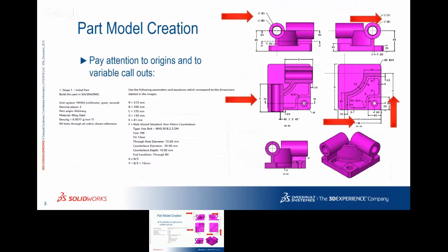So on this part, if you're missing things, like let's say you missed the chamfers, these 4 by 2 millimeter chamfers down here, that's going to affect the weight of the part. We typically tend to do tricky things like if you exclude these chamfers, we'll put that weight as one of the options of the answers. Not to trick you, but just to maybe lead you down the wrong path. So it's always important to pay attention to the drawings that we provide you.